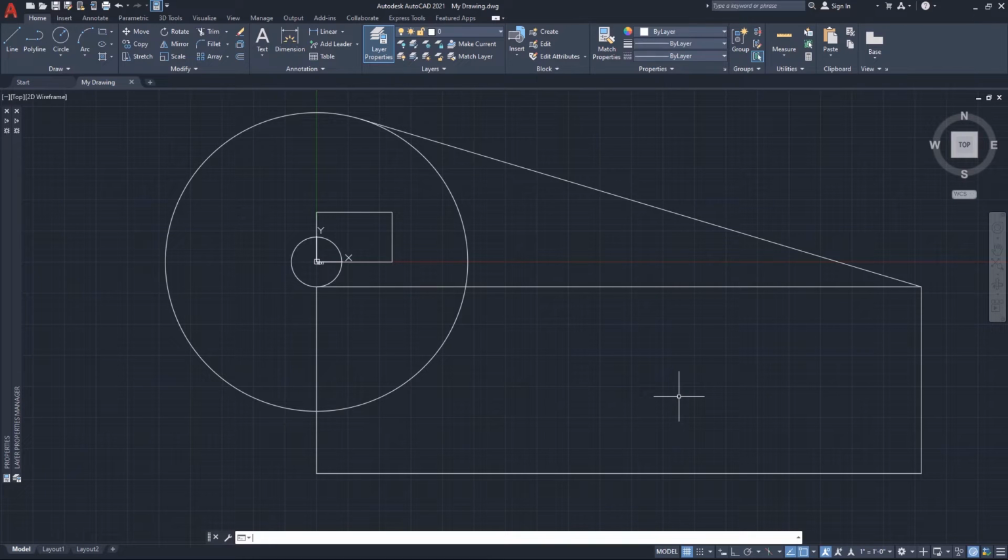Before we begin exploring the various dimensioning tools, let's take a moment to refine and define the standards we wish to apply so that the varied components display legibly for us in both model space and in our paper layouts. In our last video, we created new text styles using the Text Styles Manager.